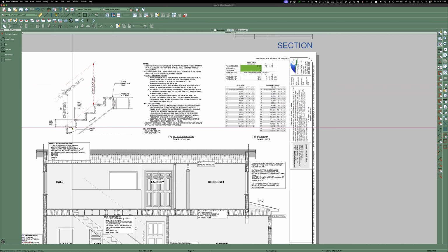And you just make a mark along the edge at the step diagonals. And then that way, as you're bringing your framing square along, you line up with those marks and trace it out, and it keeps you exact through the entire length of the stringer.